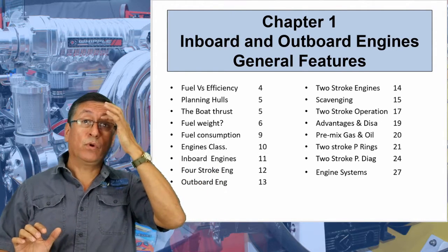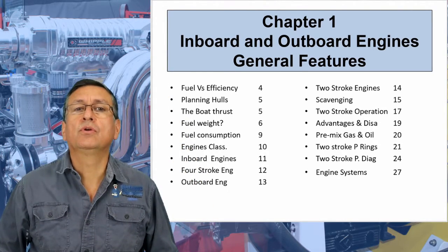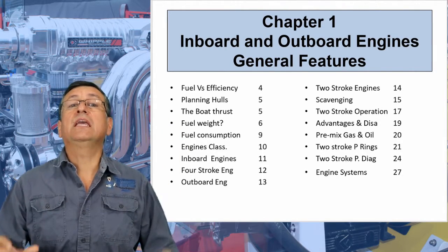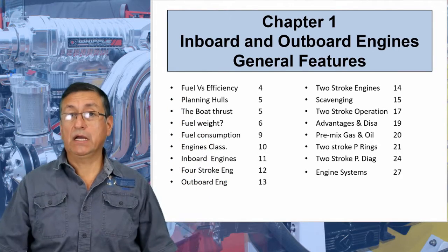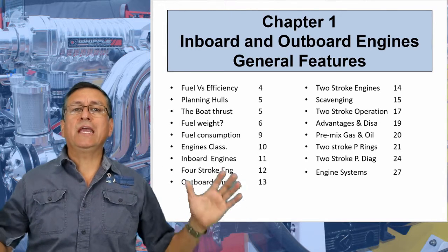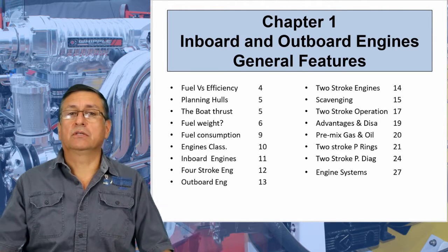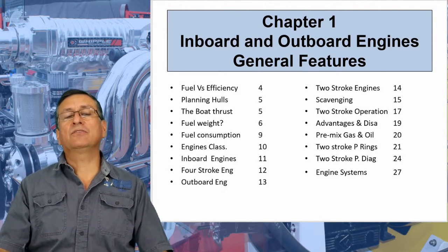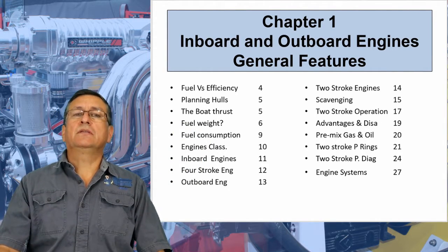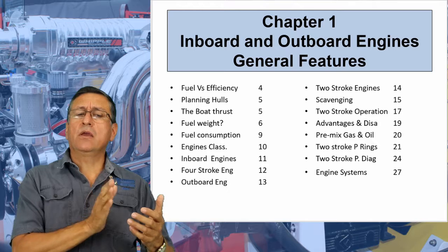And also, one important thing right now in gasoline is the use of ignition protected elements in the electrical parts like the alternator, the start motor, and the ignition system. All the electrical parts and accessories of the engine should be ignition protected, because the gases, the fumes from gasoline are lethal, right? These are the topics that we are going to analyze, and we are going to study them one by one